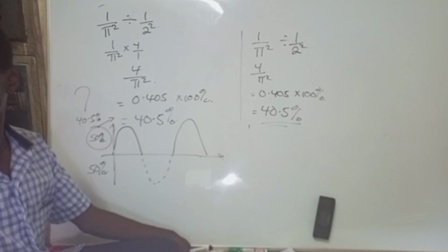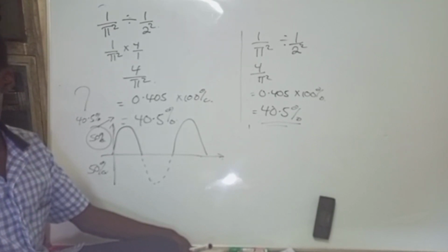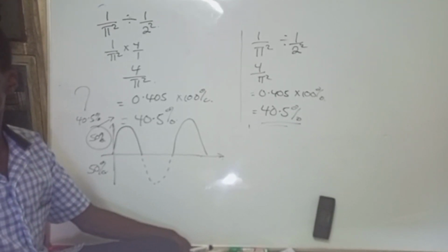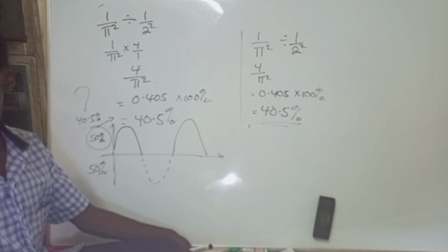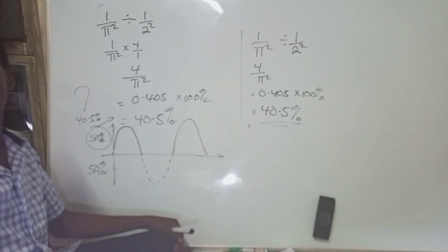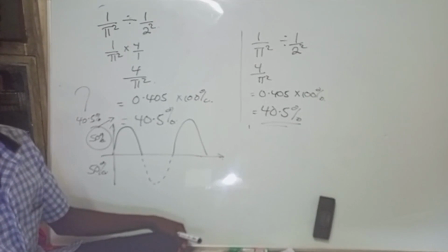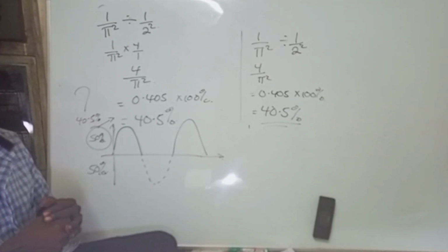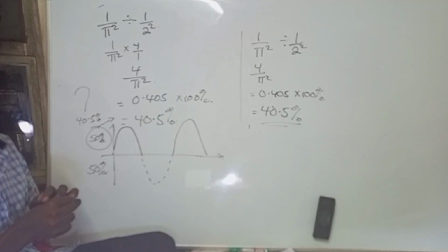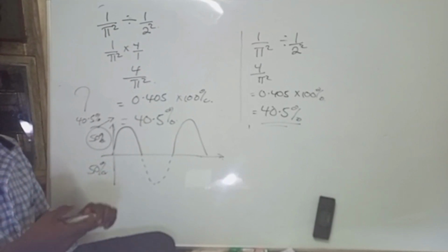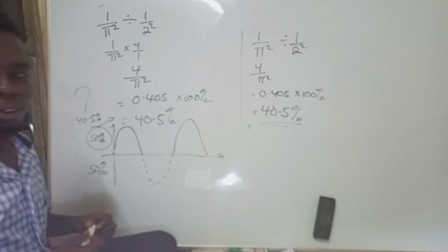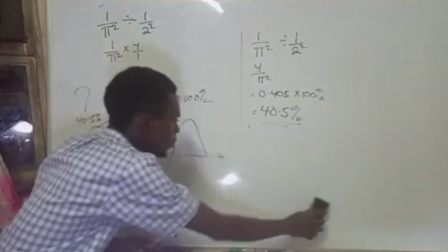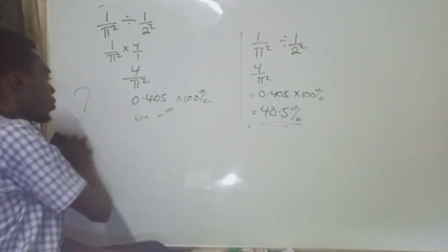So what I was saying is that this question is asking us about what happens to the rest of the power. The applied input AC power to a half wave rectifier is 100 watts, then the DC output is 40 watts. They want us to find the ratio, which is simply dividing through.